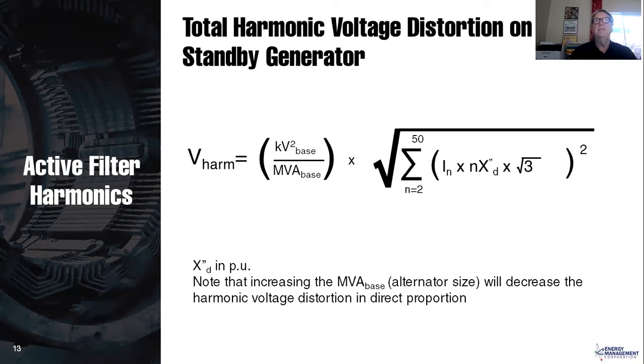Whereas on a substation transformer or distribution transformer, you know that your reactance is going to be in the order of 5.75%, routinely. And so you could say this is almost 3 times as high as the impedance of a transformer. For that reason, you get much worse voltage harmonics.